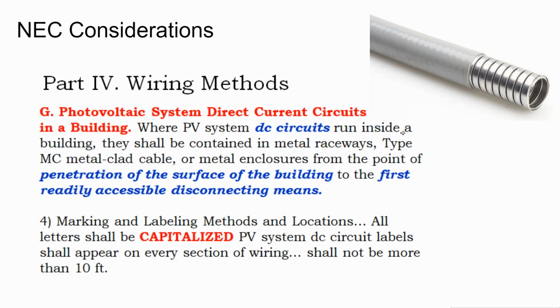I actually think that this metal conduit protection for PV systems is a bad part of code. People get the false impression that the metal is there for a grounding path, whereas really it's just there to provide additional physical protection of the conductors from being hit by people.